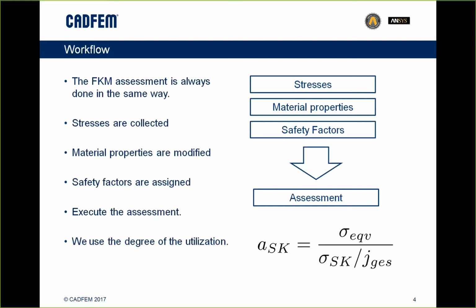So I only get the surface cool, and the core will still be awfully hot. So we have some material factors we calculate in to compare the sample we have to the real part we have. So my material properties will suffer a bit, but will then be closer to reality.